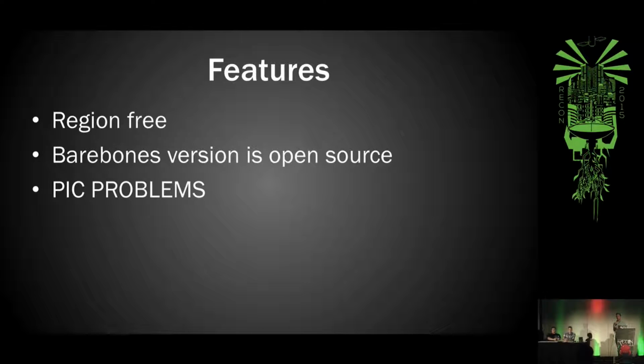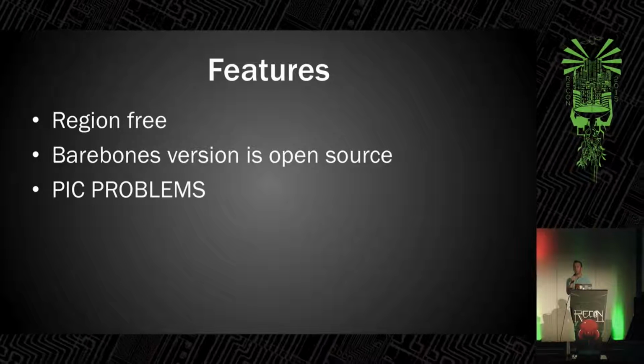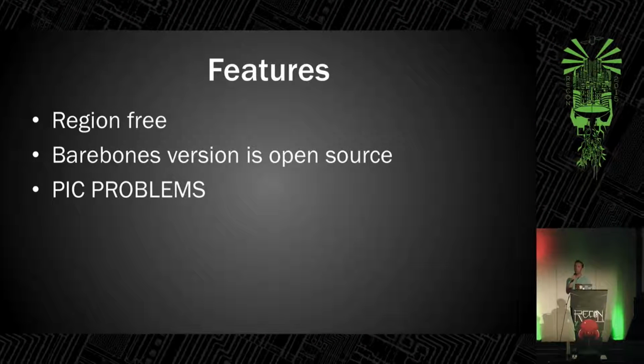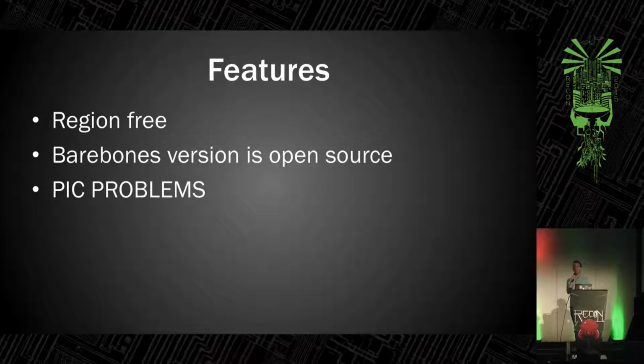So we wired up a PIC to the same clock, and we thought, great, we're going to have twice as many instructions to actually implement the same thing, because we'll be running at the full external clock speed. Well, fun fact about 8-bit PICs, they actually run at 1/4 the external clock speed. So we had half as many instructions.